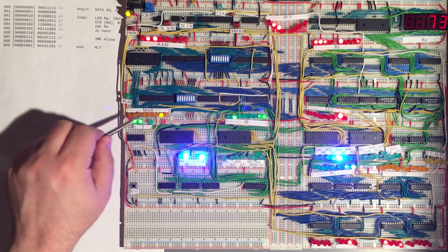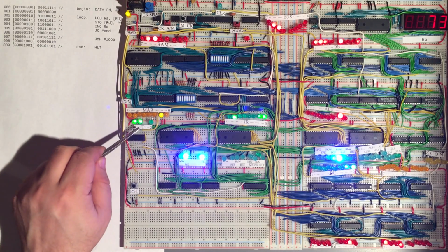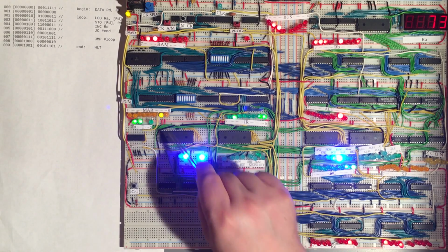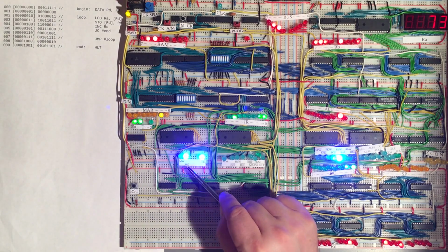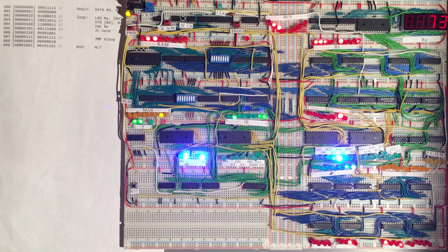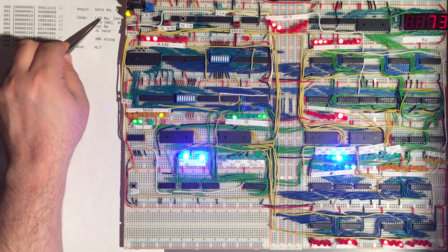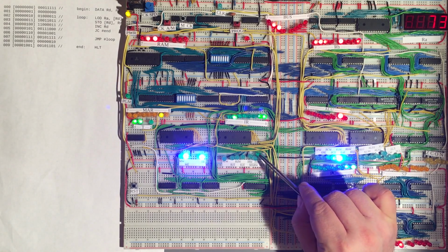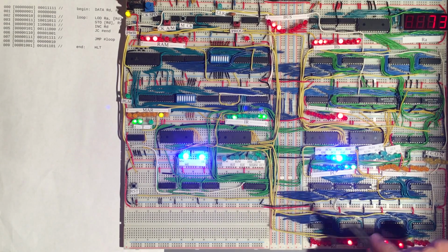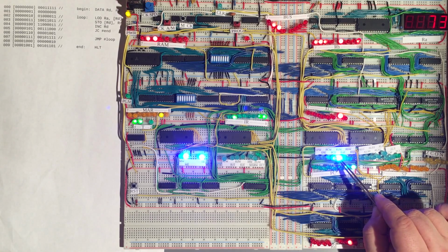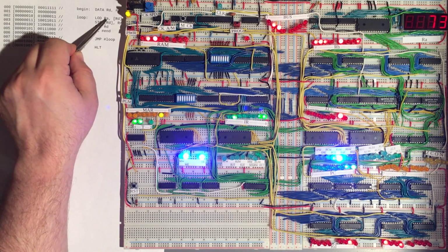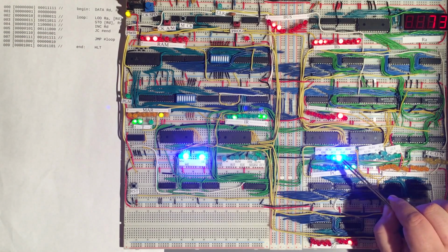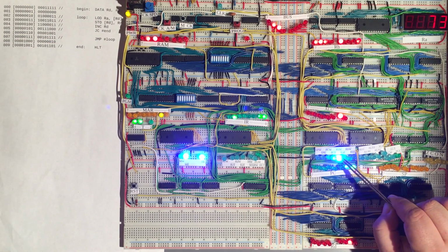So all right, that value is now in the memory address register, and so on time t3 we can then enable RAM because we've set the address register for the RAM to point at the address we're interested in. Since we're simply loading, we want to load from data memory, so we won't be asserting the program memory signal, so that stays off. But of course then we need a corresponding write signal for whatever register we want to load the value from RAM into. So in this case that's the A register, and so the A register write signal is being asserted.